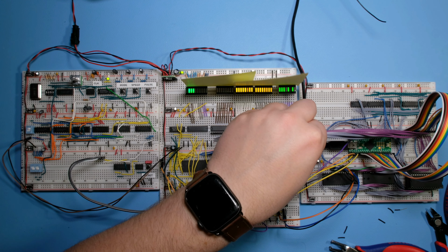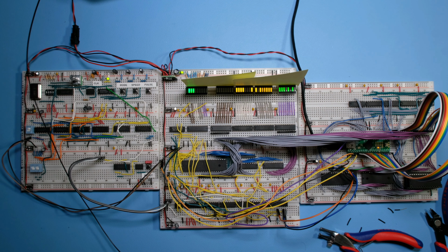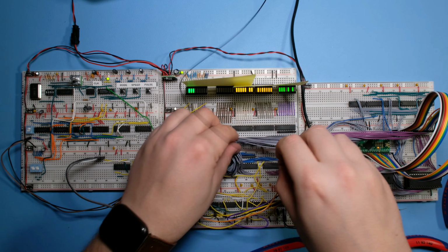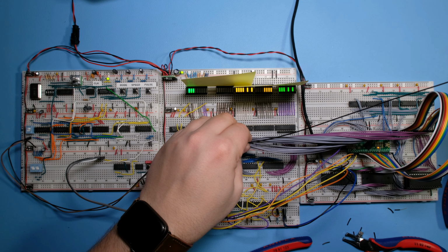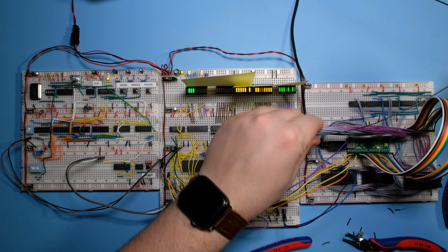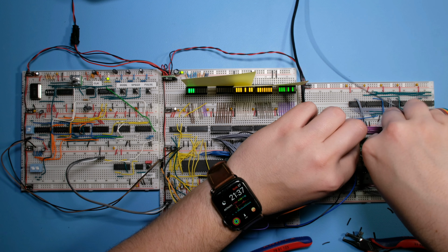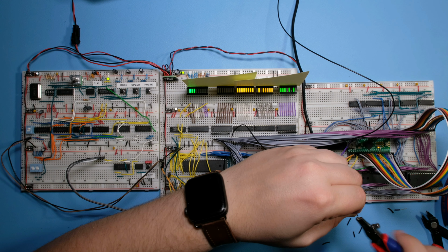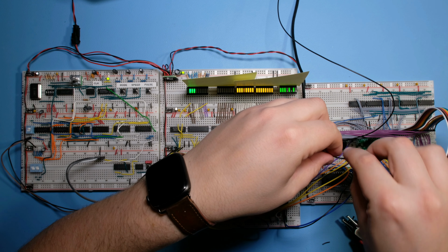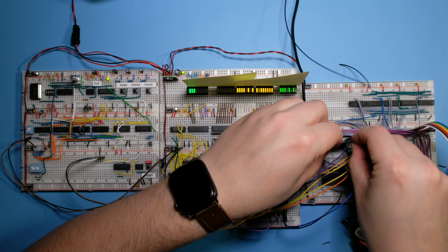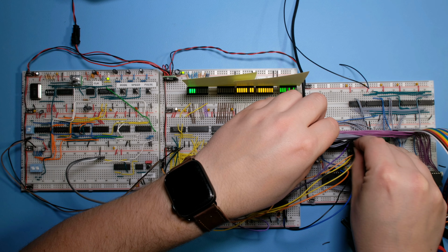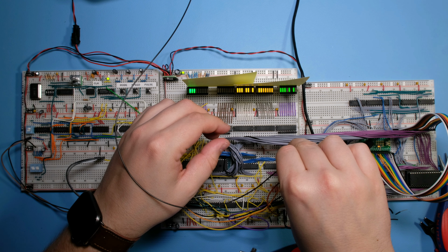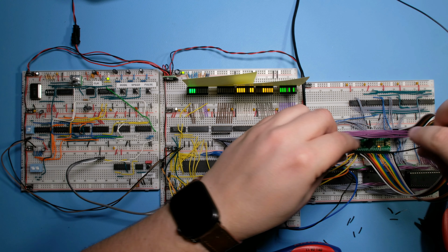Then we have the big ones over here. So we have some going this way. And then we can take ground wires for each bundle of 8 wires all the way up to here. And really what I'm doing here is I'm just trying to follow each signal wire as it goes between breadboards and connect it to the ground on the other side. And then let's say we can do one here. I guess I'll do one every 16 wires.